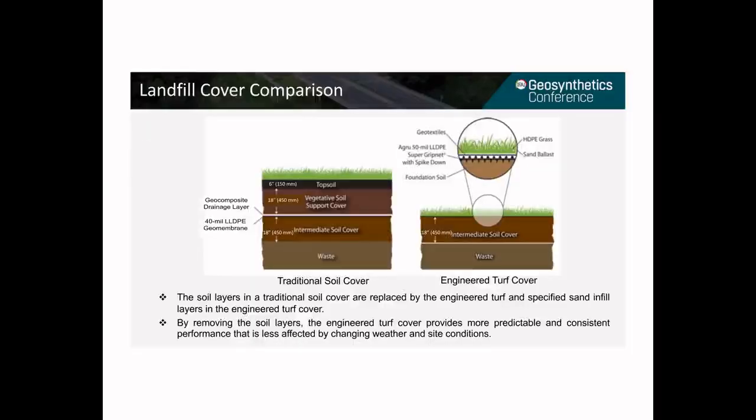As I mentioned previously, the challenges with soil covers are related to the soil layers. By removing soil layers, the engineered turf cover provides more predictable and consistent performance that is less affected by changing weather and site conditions. As shown in this slide with a side-by-side comparison between a traditional soil cover and the engineered turf cover, the soil layers above geomembrane in the traditional soil cover are replaced by the engineered turf and specified sand infill layers.